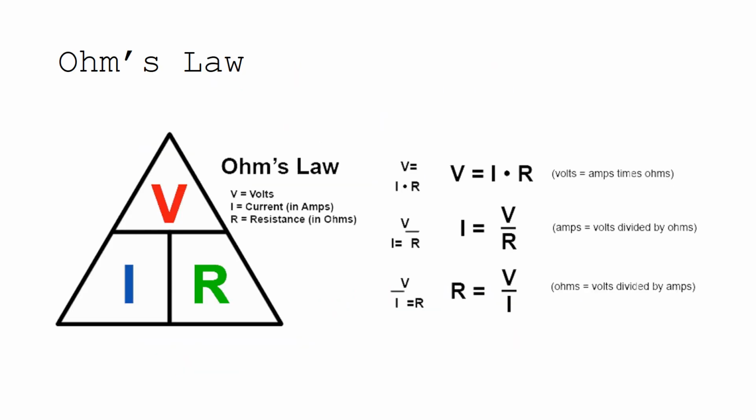So in an electric circuit, we have a relationship between the voltage, which is the main component of the power, current, and resistance. The current, voltage, and resistor are combined by what we call Ohm's law. V is equal to IR, or more precisely, I is equal to V over R. The current is directly proportional to the voltage applied to your circuit element and inversely proportional to the resistance of that element.